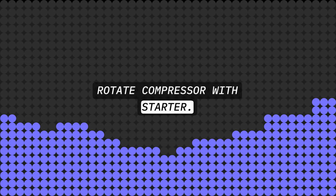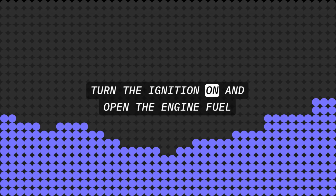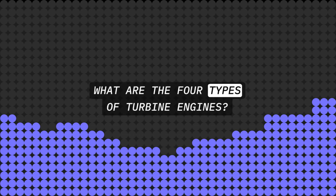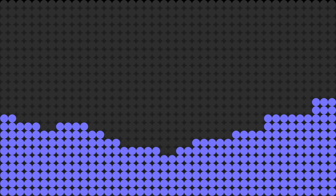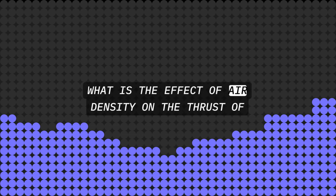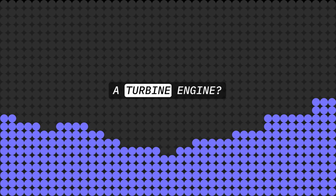Rotate the compressor with the starter. Turn the ignition on and open the engine fuel valve. What are the 4 types of turbine engines? Turbofan, turboshaft, turbojet, turboprop. What is the effect of air density on the thrust of a turbine engine?